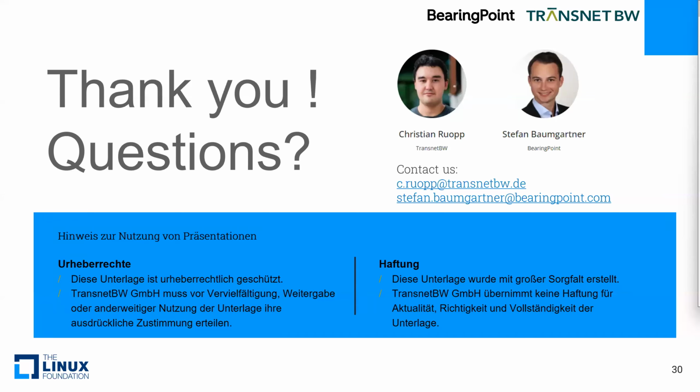Perfect. Next question: if I have prepared an SCD file using OpenSCD and then want to import it to the specific IEDs by means of an ICT tool, how would it be matched or mapped to the ICD of a specific manufacturer? Or how can it be ensured that it is exactly and correctly matched with what is available in the IED's ICD file? Right now, it's not as smoothly possible as we wish it would be.